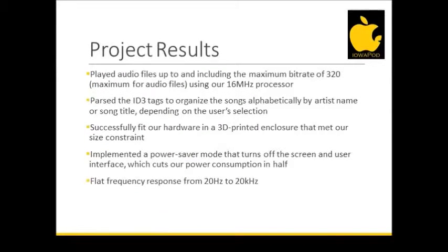But by the time we finished our project, we could play the highest bitrate of MP3 files with audio quality indistinguishable from any other MP3 player currently on the market. We were able to look at the MP3 file's ID3 tags to find the song and artist names and alphabetize them. We met our size constraints with our enclosure. We were able to implement a power save mode that turned off the screen and ignored input and cut power consumption in half. And we were able to attain a flat frequency response from 20 Hz to 20 kHz. No human audible frequencies were attenuated at all.